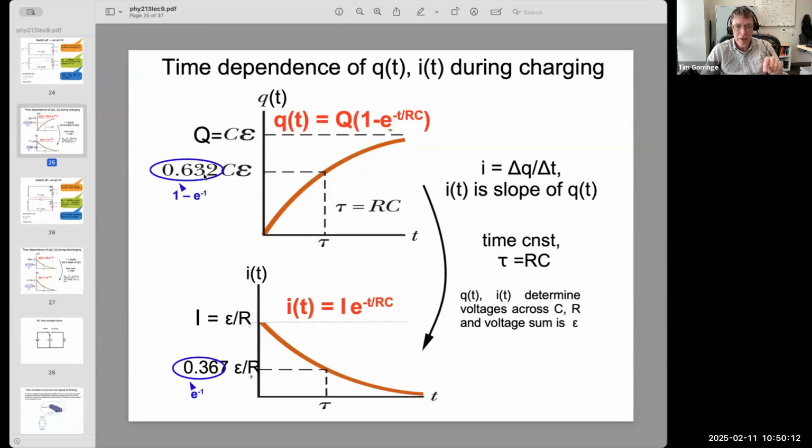So it's actually a great question that I didn't mention on this plot. One time constant gets you to 63% of fully charged. One time constant also gets you to 63% of fully discharged. If you waited 2 time constants, so that would be about here on this slide, I don't know the number exactly, but you would be 90-something% to being fully charged. You're still not quite fully charged, but you're very close to it.